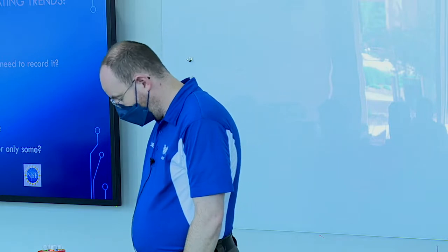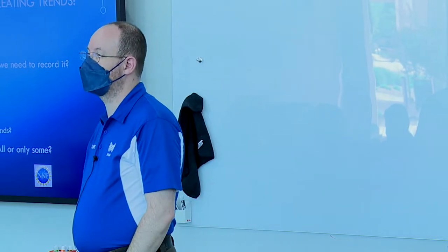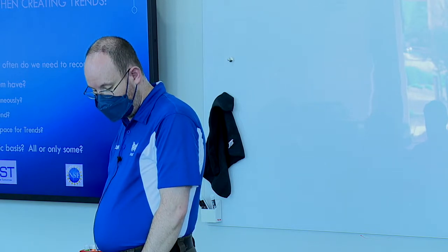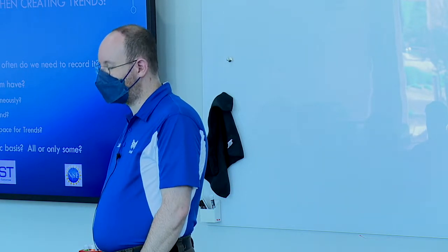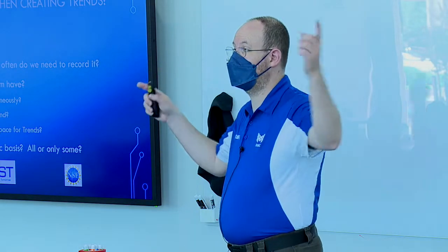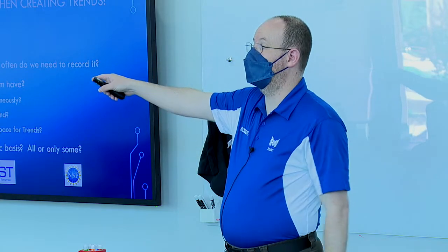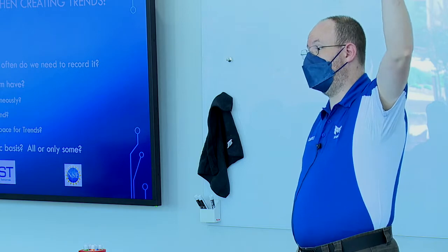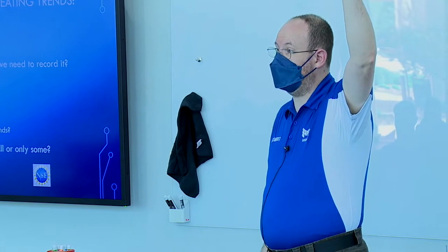What about your bandwidth? How many problems do you have if you're pulling across and jumping across both the networks? Yes, yanking data 24/7, and you're not localizing. Correct. And that kind of gets back to that BACnet conversation of how often is our supervisor pulling data from the VAV, or is the VAV pushing it when it changes, that sort of thinking.